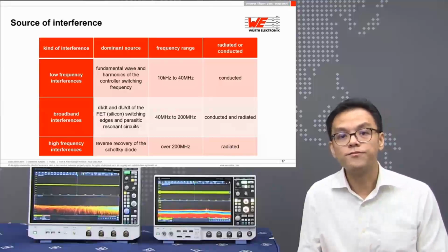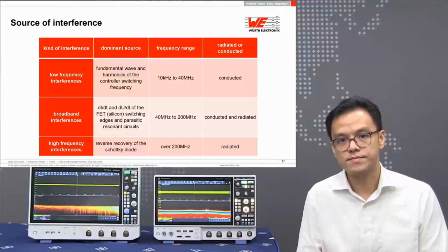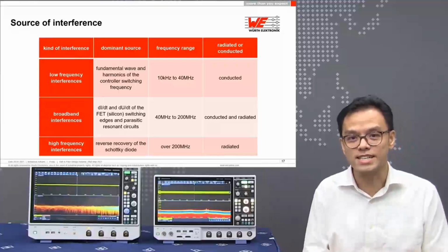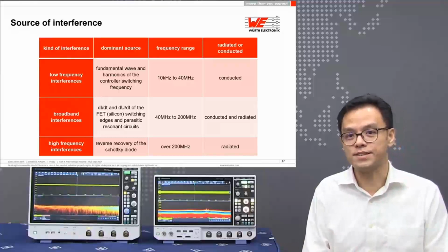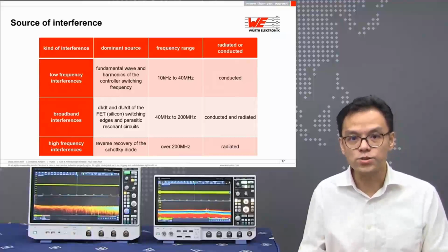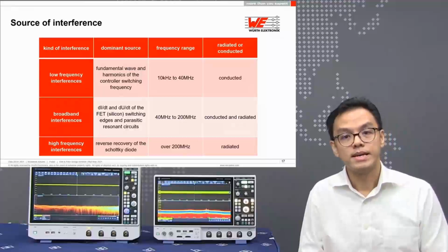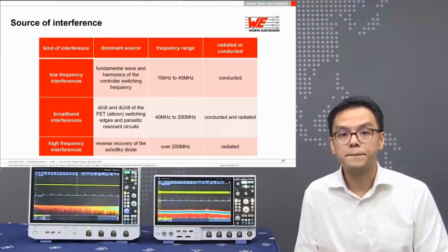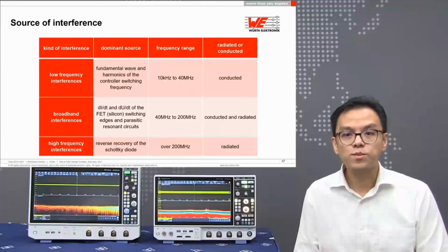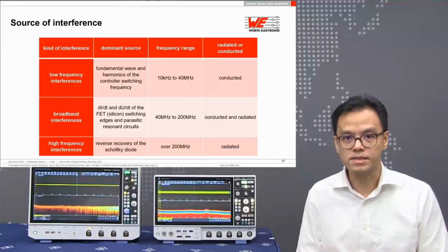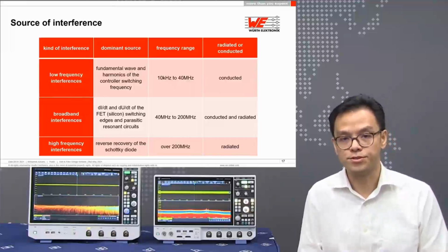Today, we'll focus on conducted emissions. If you're interested in testing and mitigating radiated emissions in your design, keep an eye on Rohde & Schwarz's events, as we regularly conduct training sessions tailored to your needs. EMC filter design emphasizes conducted emissions because they are more accessible for lab testing, especially when related to power circuits, which often require design adjustments and impact a broader footprint.